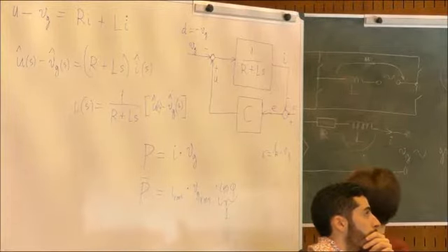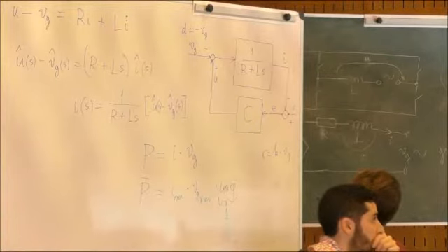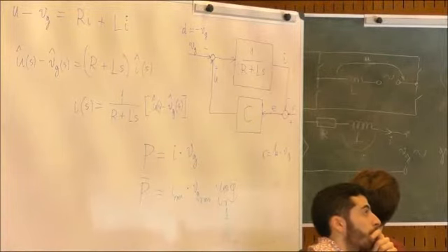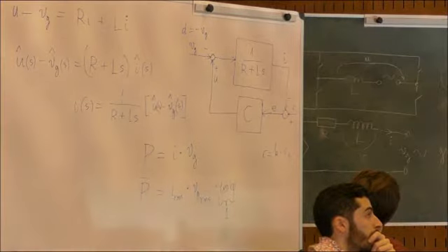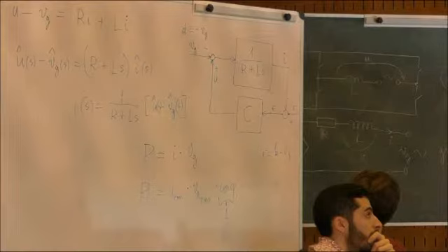You know that, yeah? Now, so you take the sum of all the Fourier coefficients which are not the fundamental, divided by the sum of all the Fourier coefficients squared. Yes? So on top you leave one out, the fundamental. On the bottom you leave all of them. And this ratio is called the total harmonic distortion.